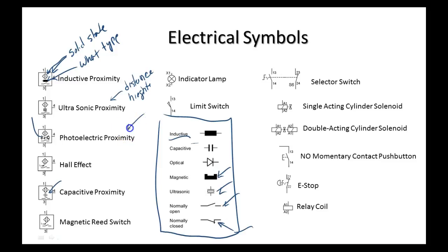These are photoelectric sensors. So these guys are going to use light. We're either going to break the light or reflect the light. And we have a lecture on sensors. But these things sense by light. By the way, proximity. Proximity is a sensor that senses when something is at a certain place. So it's not a position sensor. A position sensor senses where it's at. A proximity sensor senses when it's at a position.